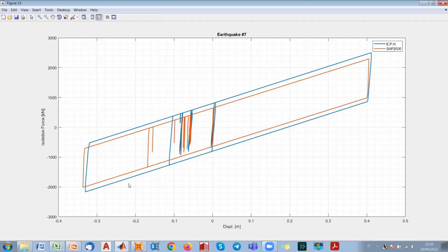And okay, here there is this additional difference, and actually there is some difference with respect to the elastoplastic, and this is directly related to, you see, the thickness of the hysteresis. If we account also for the flat slider, since the single degree of freedom response is higher, the difference will be much higher. So this can be attributed to the flat slider response, just because in the single degree of freedom oscillator, we accounted for the average vertical load, and this means that we are maybe underestimating the overall response directly associated to the friction.